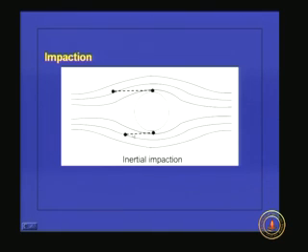Here also the same thing is happening. The water is moving in this direction. Here also the water is moving in this direction. Because of the inertia of the particle, it is not deviating its direction of motion. It is moving in a straight line and hitting the filter media. Once it touches the filter media, because of the attachment step, it is removed from the system.